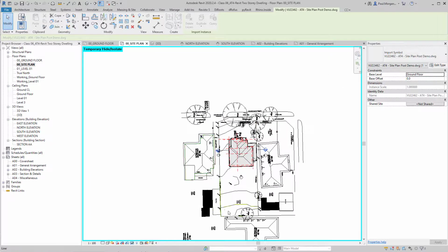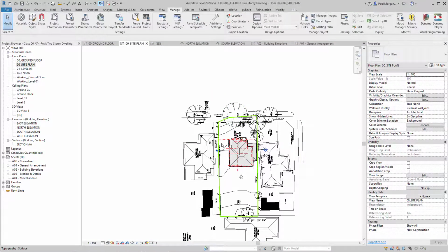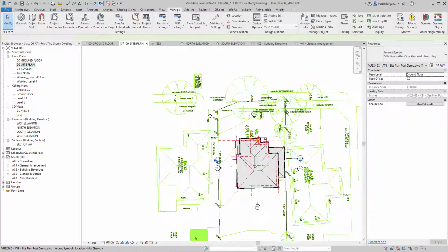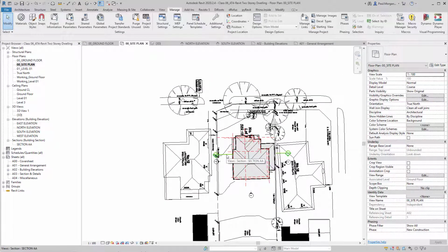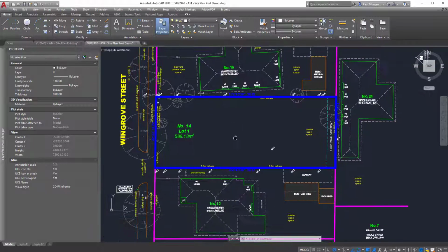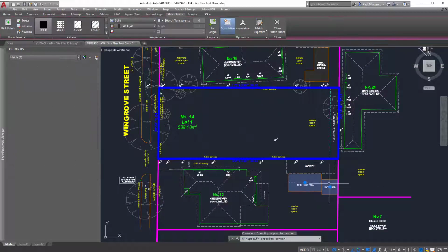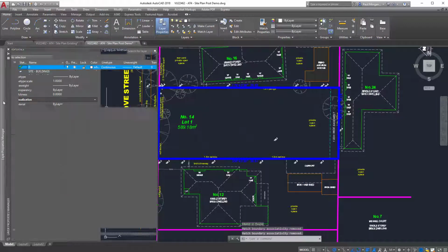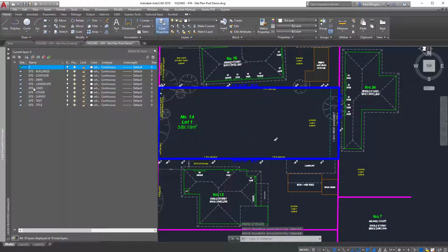That kind of works, but it's actually hidden some of these other lines here. So I can tell that in that CAD file, that's not completely clean. The title is picking up not just our site, but some of the other sites too. So, oh no, that was right. Maybe I'm just missing those lines in general. But anyway, that's how we go back and forth. So you can either delete them straight up in CAD, but I'd be a bit smarter about that and put them on respective layers and delete those hatches. And let's just say I'll create a new layer. There is one for text, but yeah, so there's a few things that come off there.